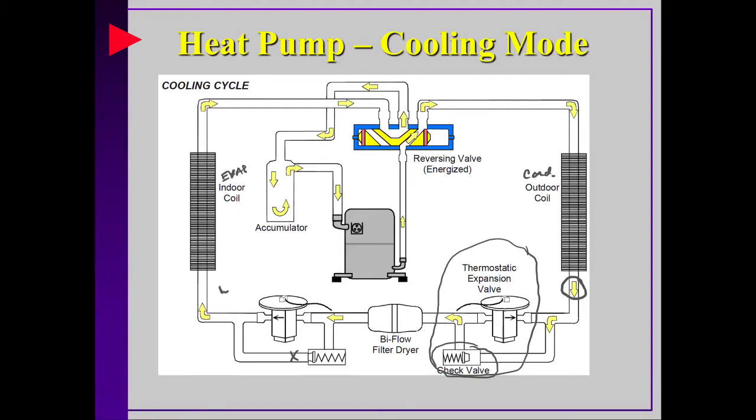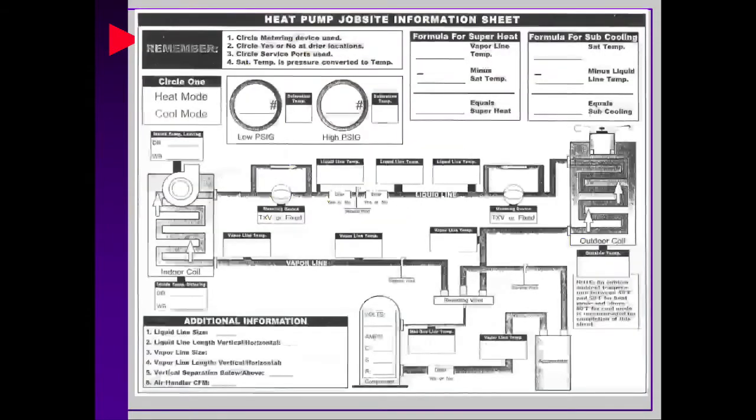So this indoor coil, which is now the evaporator indoor coil, is going to now be your low pressure, low temperature saturated liquid vapor mix, and then of course this will act, it has to absorb heat. So just like any cooling system, very similar operation to a normal cooling application.